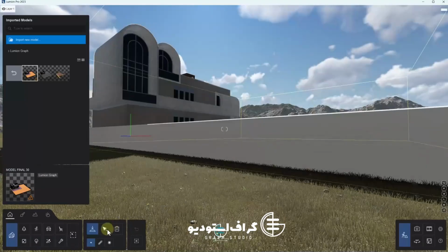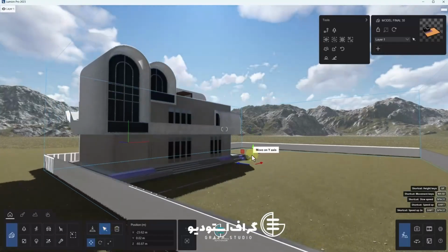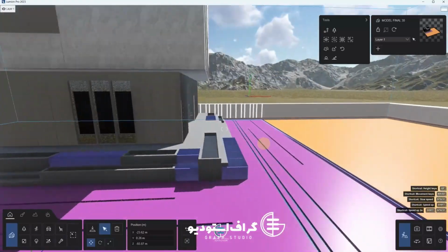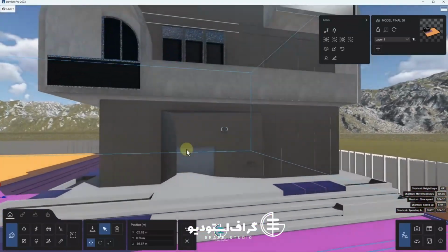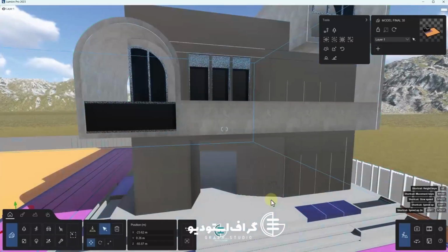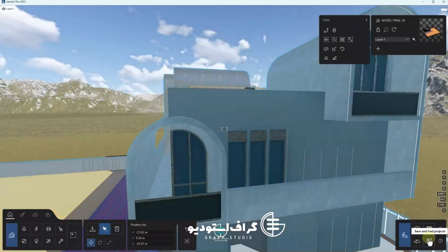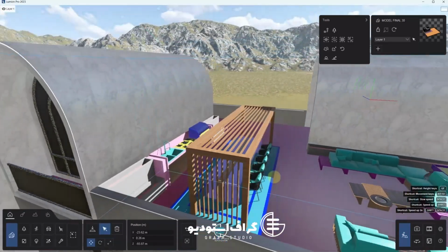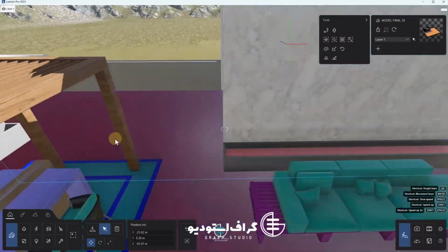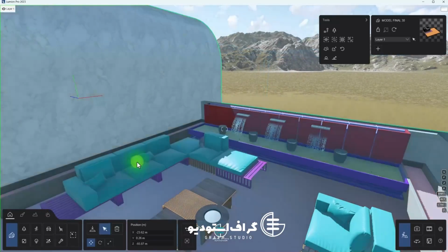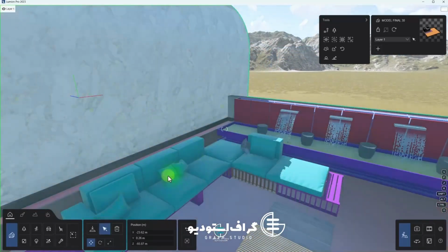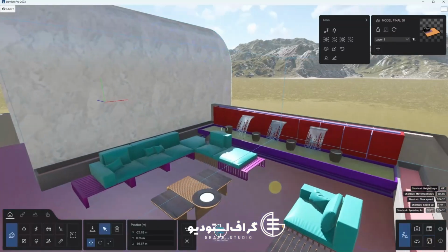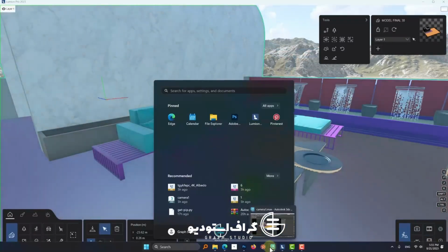One more point, the yellow box you see selected is a plane we want to assign a water material to, as per the request of the client, the engineer. We want these pots and stones to appear as if they are underwater. It's not difficult. We draw a regular plane and place it exactly where we want. If it's slightly too high or low, we can move it within Lumion, so we don't have this kind of problem either. Look, I detached all of these and assigned one material, so I can give them, say, a dirt material, or perform sculpting operations on them.